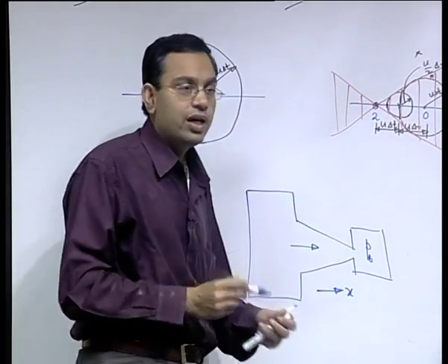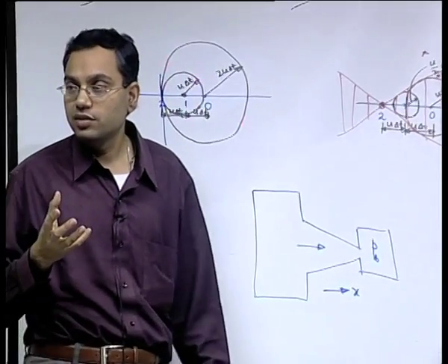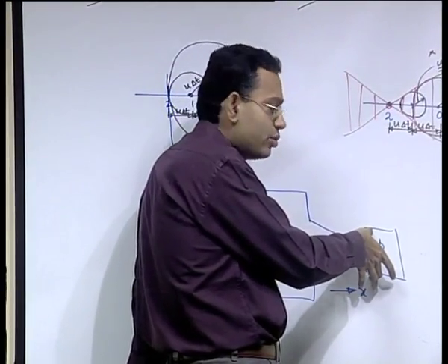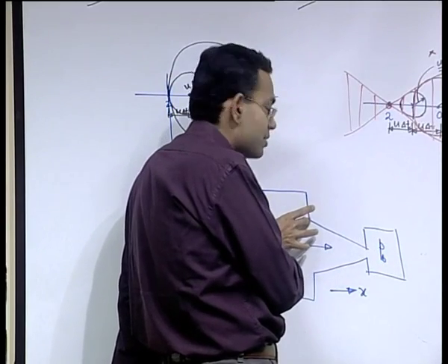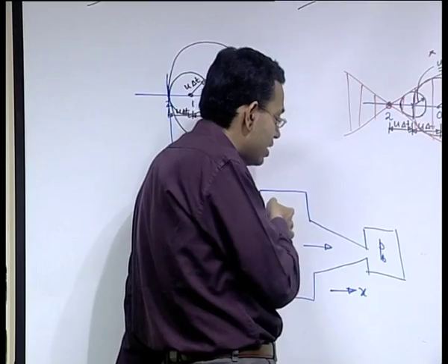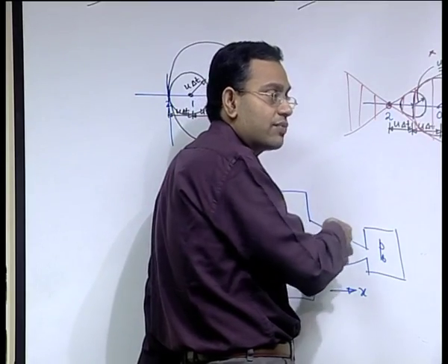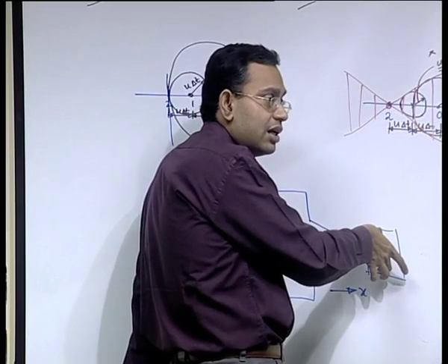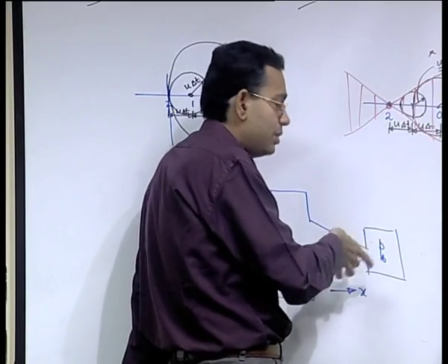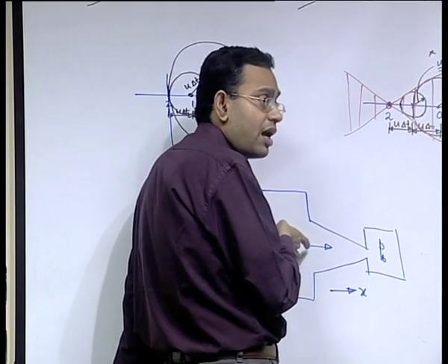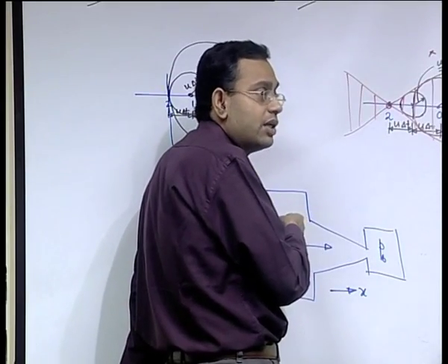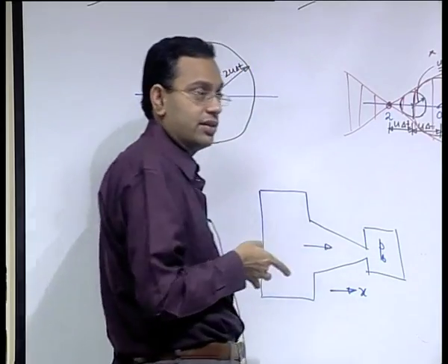So what you are basically doing, say you are trying to increase the flow rate. So what you do, you reduce the back pressure in this chamber. Once you reduce the back pressure in this chamber, this supply reservoir will know that now I have to send more fluid at a higher rate. So it will start sending fluid at a higher mass flow rate. So this back pressure regulation is like giving a pressure perturbation or a pressure disturbance into the flow medium that propagates upstream and gives a message that, well, now I have reduced my pressure, it is now your responsibility to respond to that and send more mass flow rate.